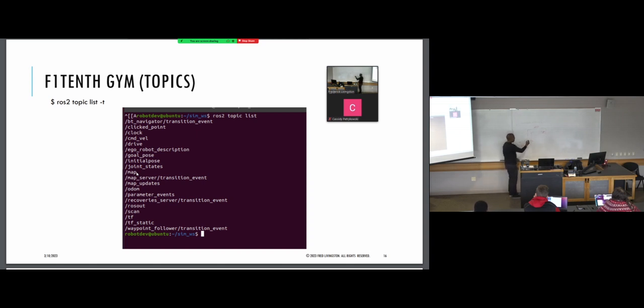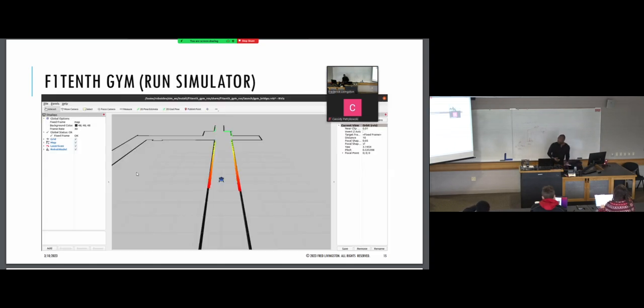You can manually drive your robot through, and that's why teleoperation is really helpful. It's going to build this map, and then we can save it. Once we save the map, we will have our own map of the environment. That's what they already provided for you in the simulator, but that's how you build your own map. We'll walk through those stages in these slides. These are the steps we're going through in this slide deck. Just think about this big picture.